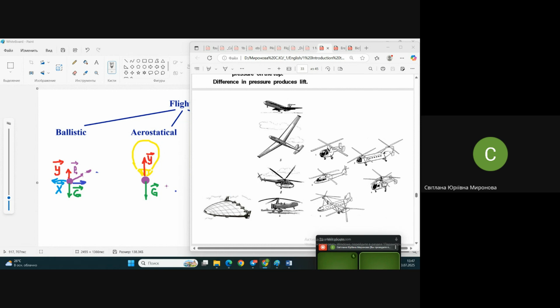But they have limitations. This machine uses an additional effect, the so-called ground effect. It's something like reflection of air from the ground, which creates an additional force, additional lift, for such a flying machine. But these ekranoplanes are able to fly effectively only over flat surfaces, quite clear, and not at big heights.